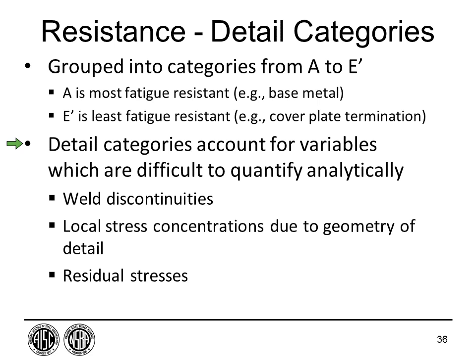So for example, weld discontinuities. Now we make good quality welds. You already had sessions on fabrication. But in every weld, there's small, tiny little imperfections. You could never figure that out in a finite element model. You could assume things, but it's a random problem. The local stress concentrations at a weld toe, for example, that all varies along a weld toe, and that all affects fatigue. It's very difficult to quantify.